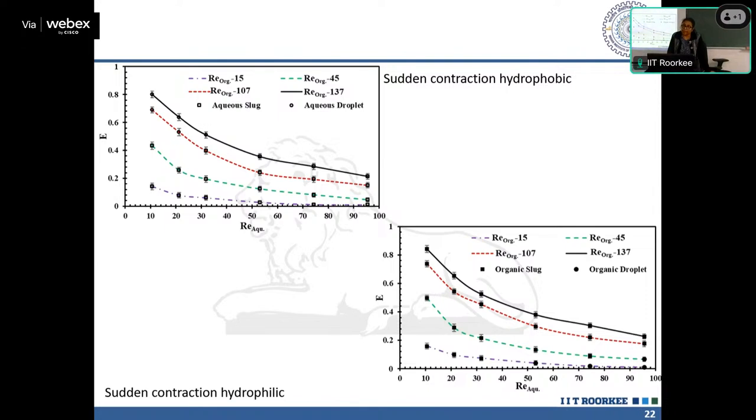Yes, again, if you vary the geometry or the cross section, it will contribute to the hydrodynamics. Even if you take a different inlet, it will give you different hydrodynamics to a certain extent. Of course, you need to test how much is the contribution if I vary the inlet configuration, the shape, or the hydraulic diameter.